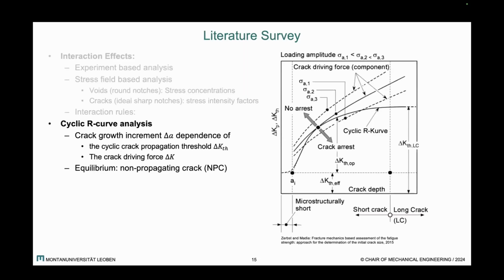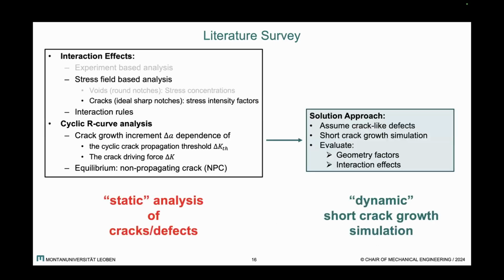The other keyword in my topic title is the cyclic R-curve analysis. This is to find an equilibrium point between the cyclic R-curve and the evolution of crack driving force as the crack grows larger. And there we can find a point of maximum non-propagating crack dimension.